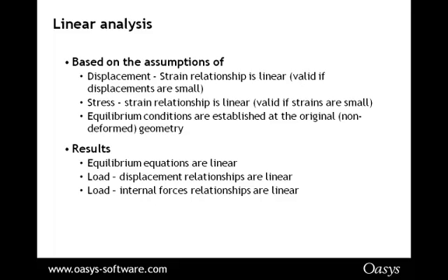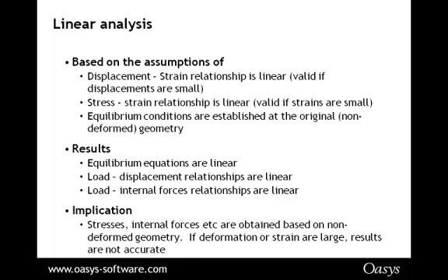What this means is the end results are linear, low displacement linear: you double the load, you double the displacement, and load forces are linear, you double the load, you double the bending moments, shear forces, and so on. What this means is that you can combine the results. Of course, it's all based on the non-deformed geometry, but if you get large deformations or large strains, you're going to get inaccurate results.